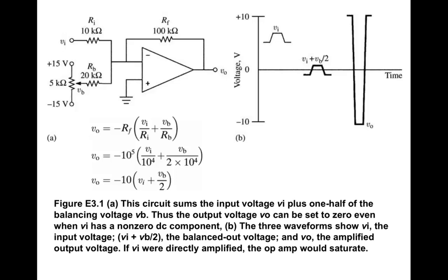An example of this: it's not at all uncommon when making an EEG measurement that you have some DC level in the background of your voltage that can come from a number of sources. A lot of times it even comes from, say, the fact that you have some DC on your ground. So because of this, what you would like to do is take this little signal V sub I and shift it down so that it's centered around the 0 voltage axis, and that way all of this would then be amplified by the input resistor.